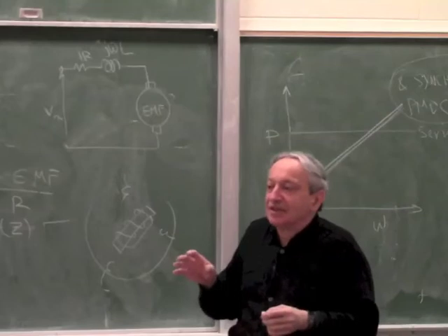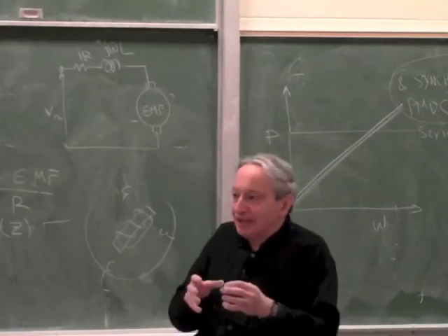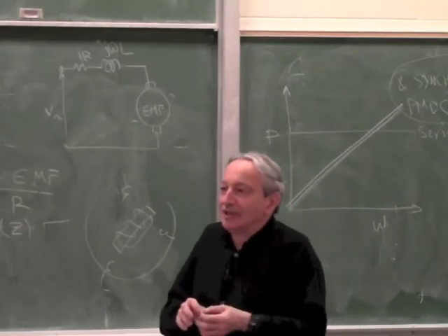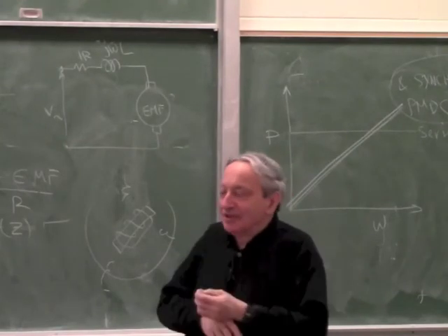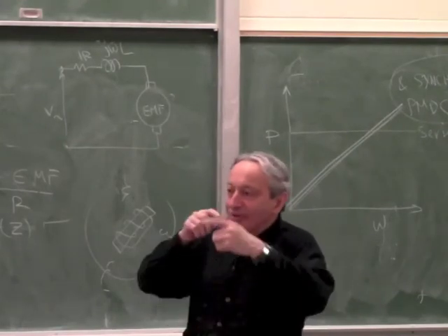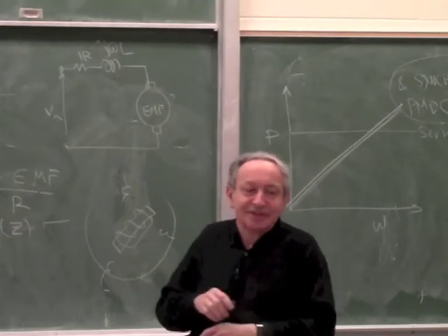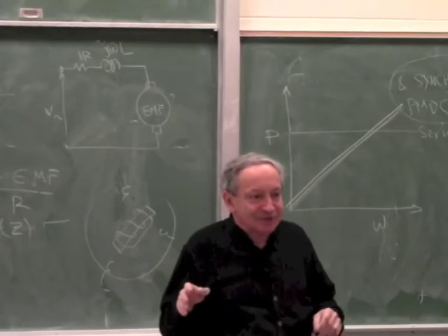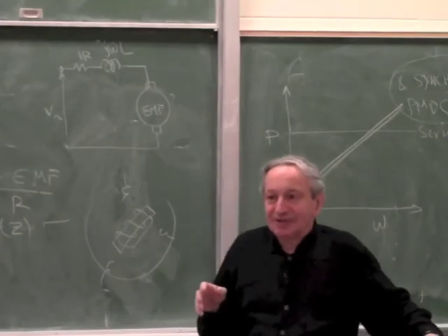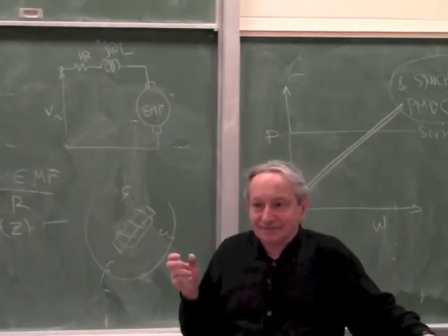That is exactly the reason why cars used to have a dynamo with brushes and got replaced by an alternator, which has slip rings but no sparking. Because the slip rings are continuous, they don't interrupt the current, there's no sparking. That was a huge improvement to put alternators instead of dynamos in cars, because there's nothing to wear. Okay?